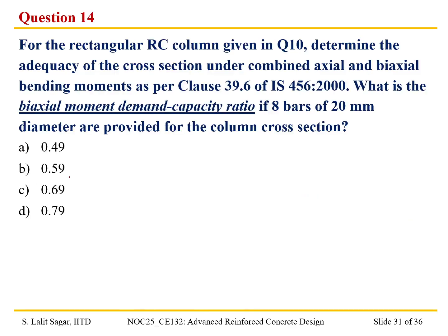So once we have the modification factor, okay, then we can proceed to find out the accurate moments, that is MTX and MTY, that is MUX plus K into MAX, right?